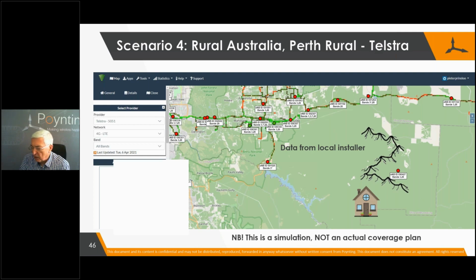And again, this is a simulation. I'm not saying that there is actually such a mountain range, but the bottom line is the installer tells this chap that that's the only tower that you unfortunately have a signal from. We know that it's quite a distance, and that's when we realize that we're going to have to go to the higher gain of a log periodic antenna.